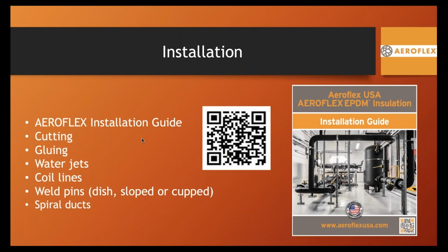This product is closed cell, so it is not intended to be used as a conformable product on the inside of ductwork at 90-degree angles. Important to note, weld pins, we recommend dished, sloped, or cupped pins so that they don't puncture the skin of